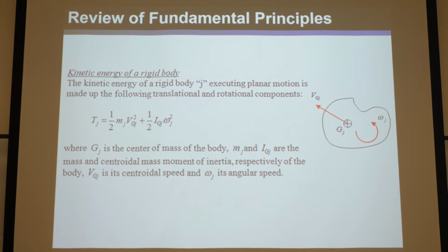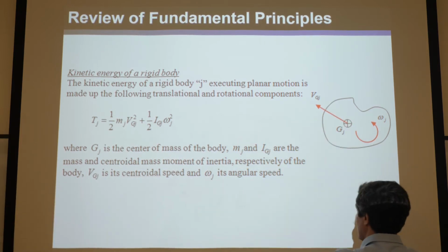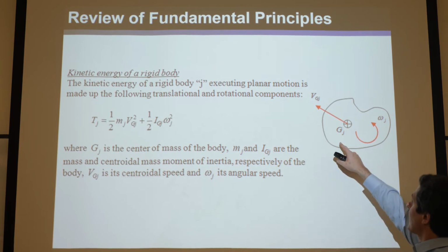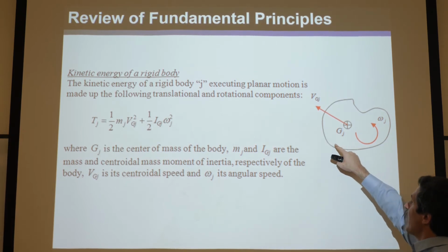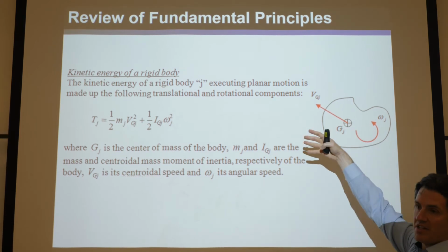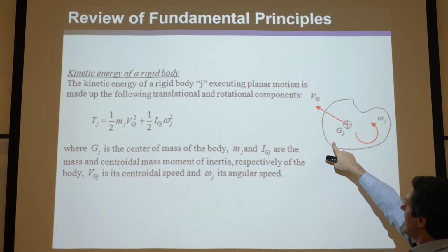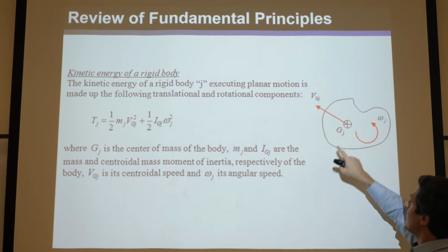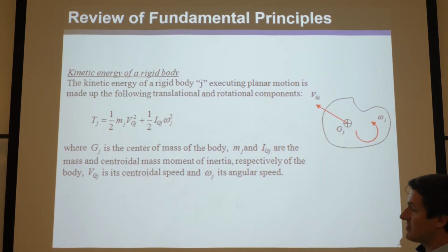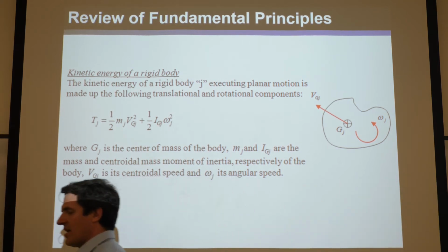But just a little nuance, the question is which speed, right? Because if you've got this potato and say it's rotating, flipping through space and translating, every velocity vector at different points could be very different, especially if it's rotating. Like say it was rotating on this axis, well at that point it would be zero velocity and all the other ones would have different velocities, right? According to the velocity difference equation.